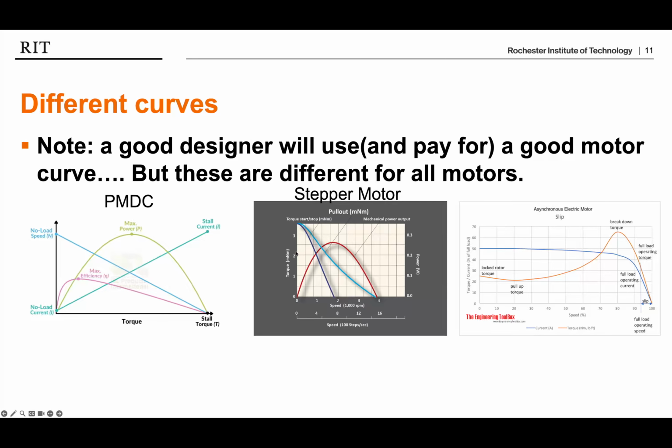Okay, so there's a reason we don't have current plotted on here because it's not irrelevant, but it is not as relevant as we would think. These steps and the speed are really controlled by coils flipping, not like traditional current. The other thing that is suspiciously missing is our efficiency, because whenever these things are not moving, they're not efficient at all. So sometimes you will find maybe an efficiency plot, but it's usually not something we're concerned about.